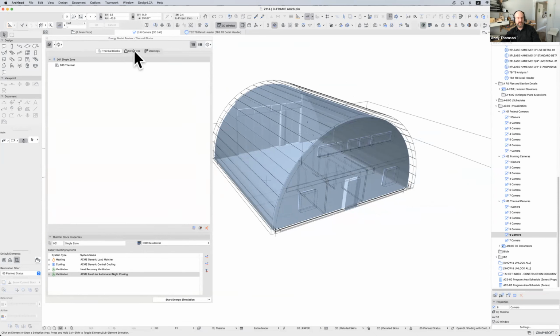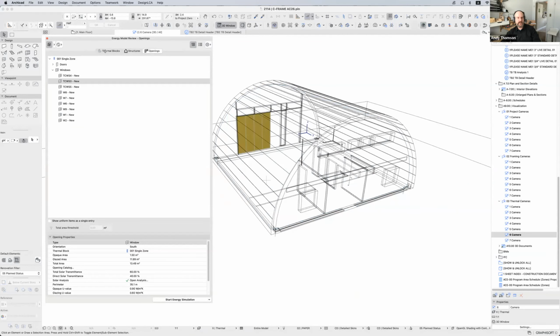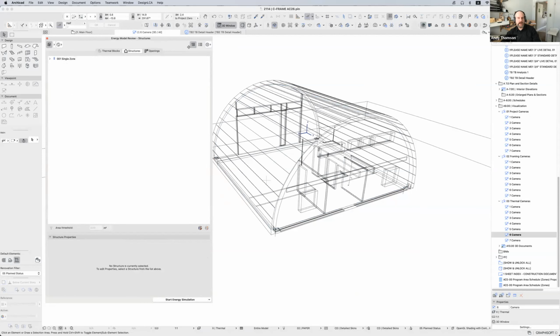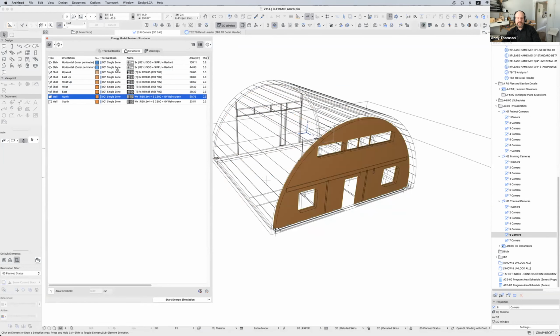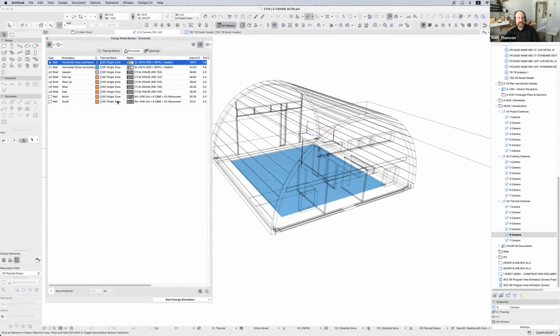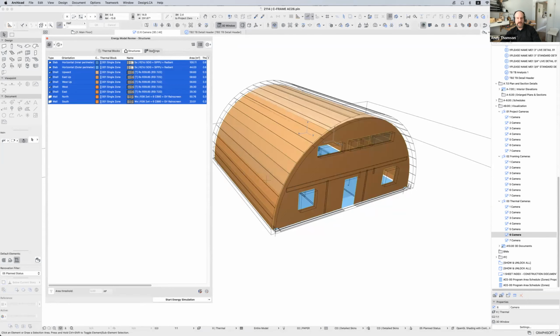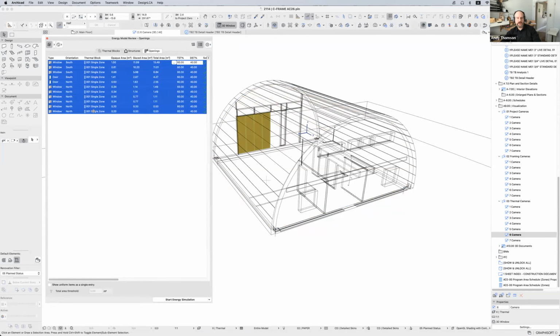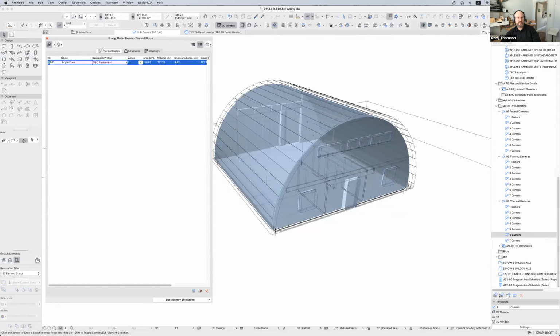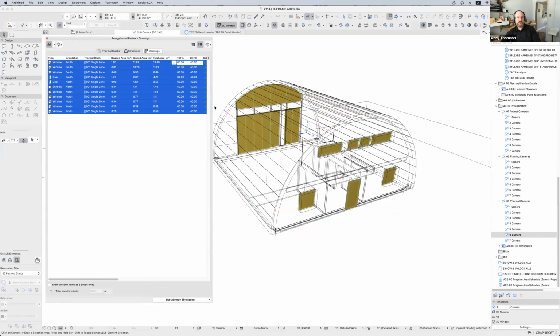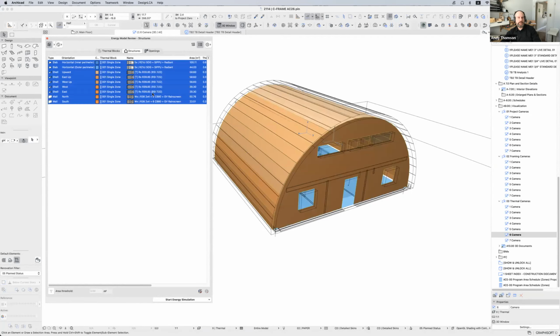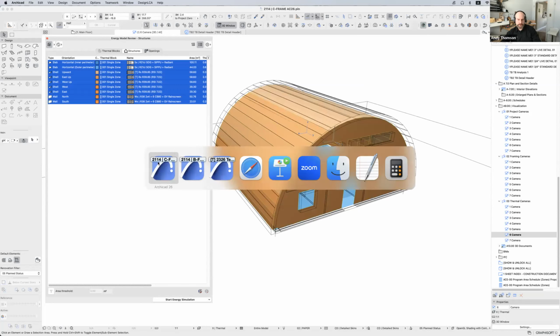So we've got these 3 tabbed pieces up here: structures, openings, and thermal blocks. So I've got structures, and I've got this tree view, and I've got a list view. I can pick on the list view, and I can go one by one to see how EcoDesigner or Energy Evaluation has captured all the surfaces. Did it get everything? And I can pick all of them to see that all together, right? There's my structures and there's my openings, right? I want to make sure that I've kind of got the whole model defined. So all the windows are captured, all the structures are captured, and all the zones have been included in this thing. So sometimes you will get structures that have a high value or a low value.